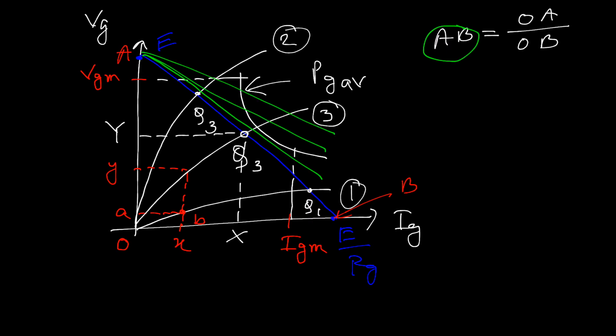So for designing purposes, the optimal value of RG can be defined by a particular slope which is just tangential to the average power graph, defined by, suppose, OC. This is called the critical resistance, just like in a machine. This is the maximum slope of the load line or resistance line up to which the gate to cathode current can easily conduct.